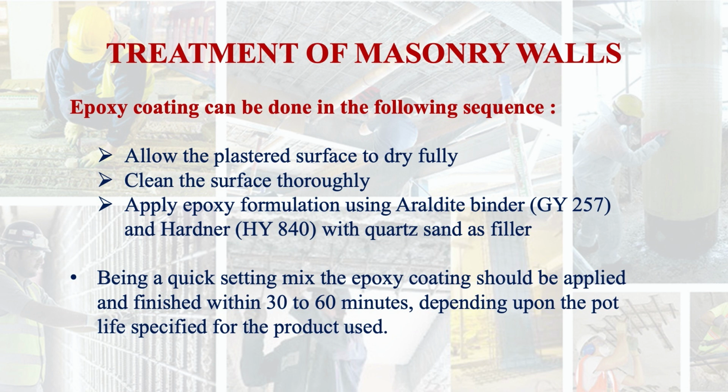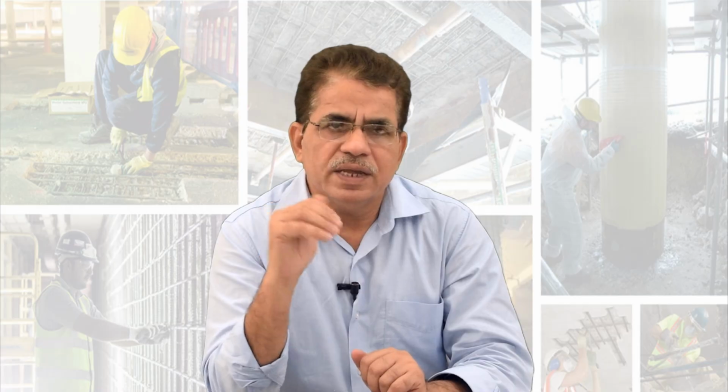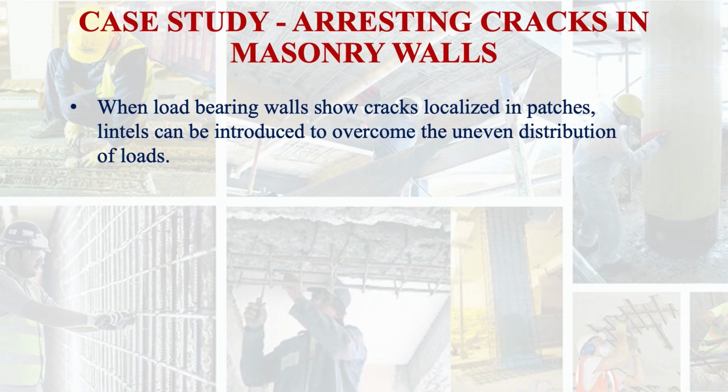Being a quick setting mix, the epoxy coating should be applied and finished within 30 to 60 minutes depending upon the pot life specified for the product used. Now let's move to a case study of arresting cracks in masonry walls.